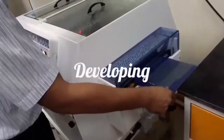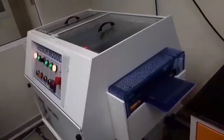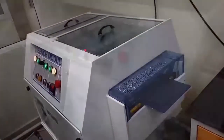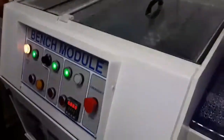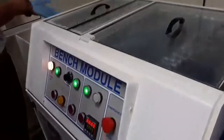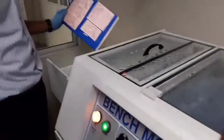Fourth step is the developing process. Developer is used to chemically remove the unexposed photoresist. The board is rinsed with water to wash away the excess chemical. Solid traces and a clean copper background are considered a well-developed board. This is the result.